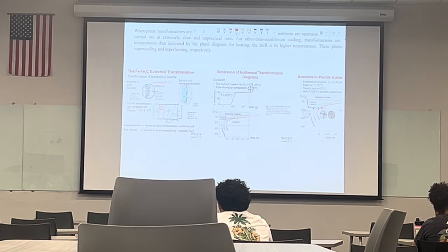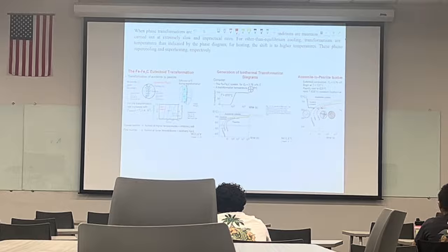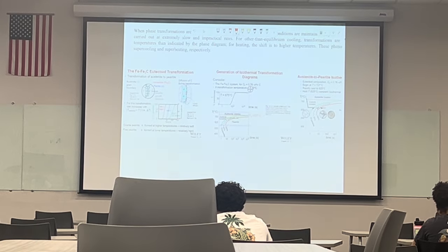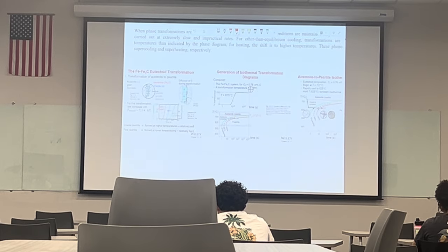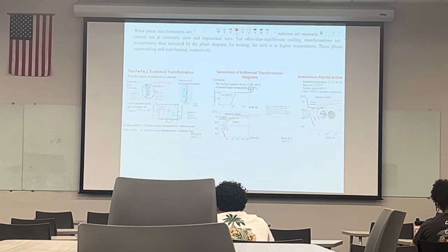But here, you can show it in another figure like this one as well. That's the eutectoid temperature, the orange line. In the previous chapter we saw that below that temperature we don't have austenite anymore. But in reality, if you cool it pretty fast, the system doesn't have enough time to transform all the austenite to another phase. That's why we have something like that, right?